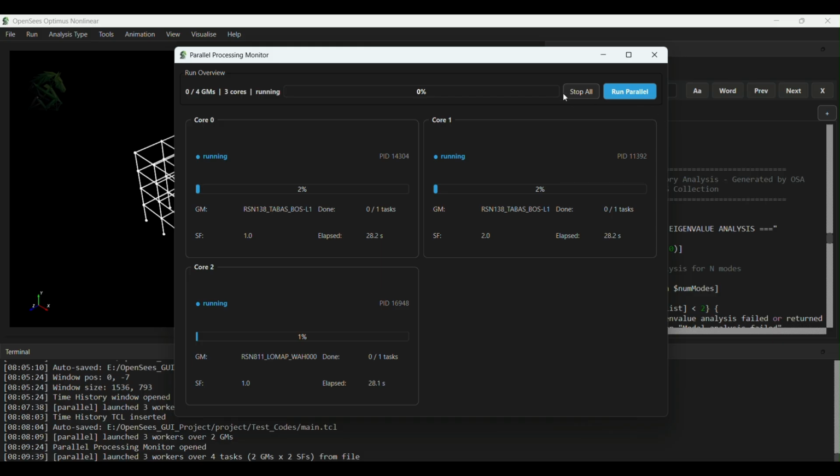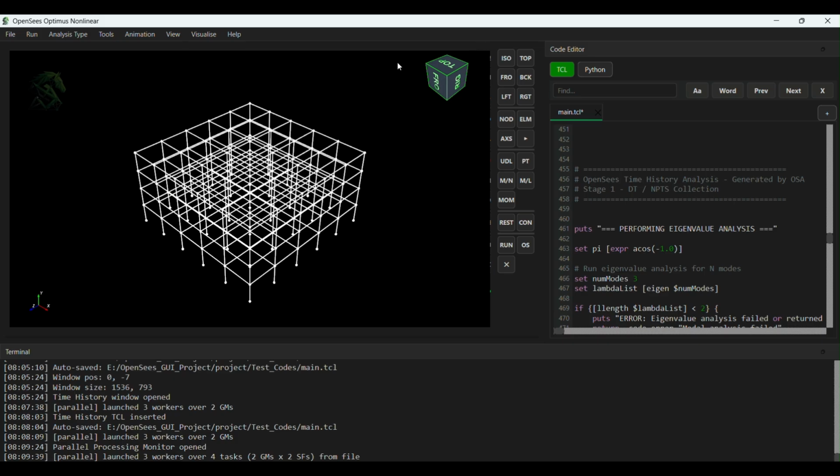Working order, in summary: load ground motions, generate or import a target spectrum, scale the records to it, inject the resulting code sequentially or in parallel, then run the analysis.